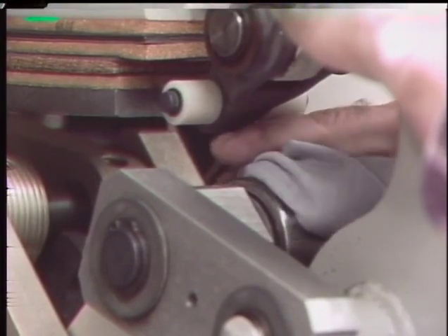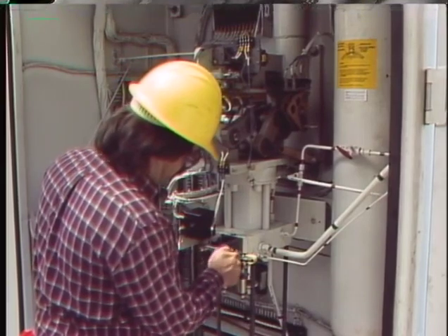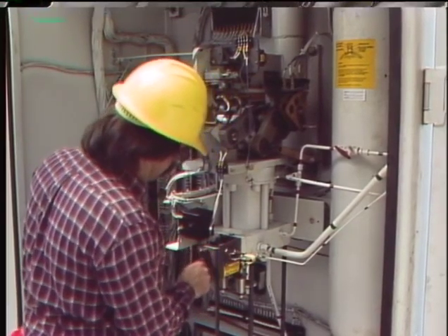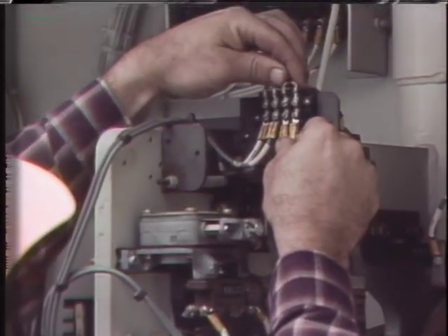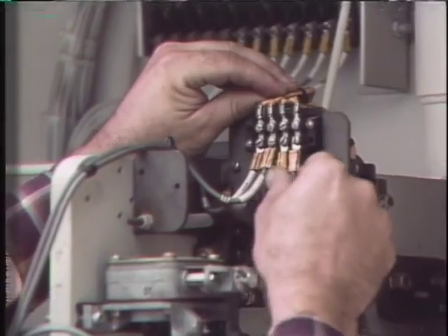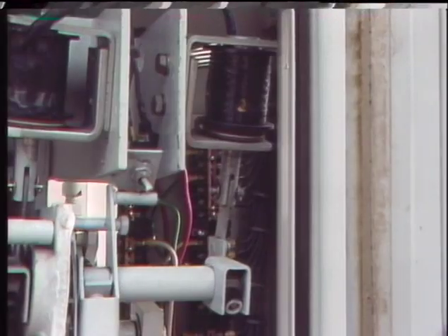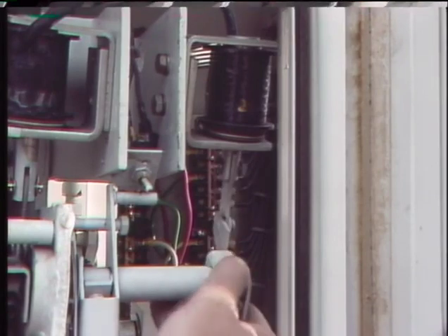Parts with excessive wear should be noted for possible replacement. Check for loose nuts, bolts, and screws, and tighten any that need tightening. Also, check for loose wiring connections or wiring that's frayed, cracked, or corroded. Plungers on control coils are checked to see that they move freely.